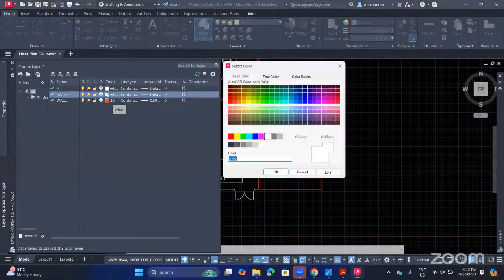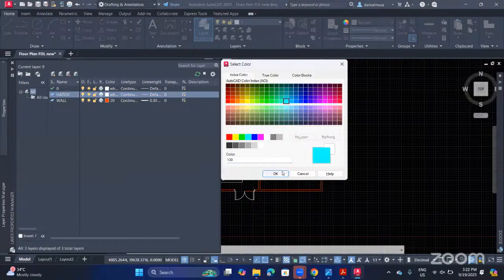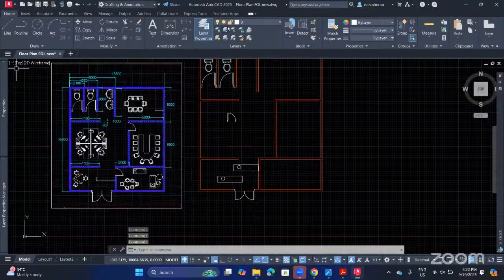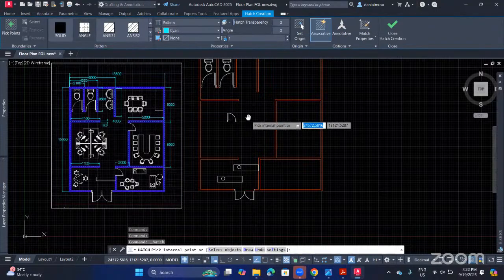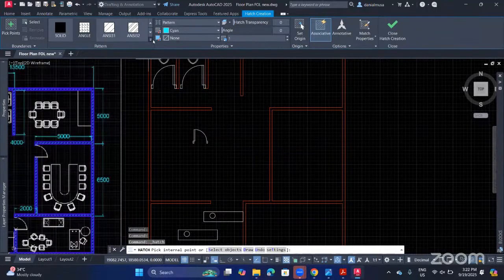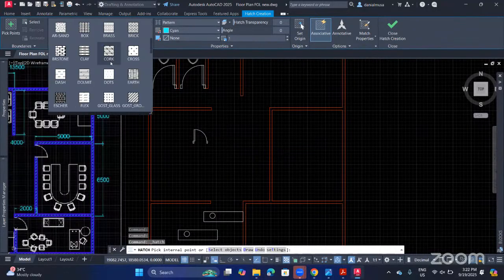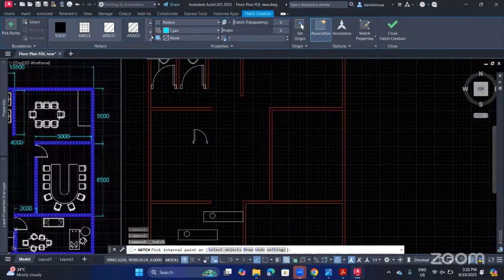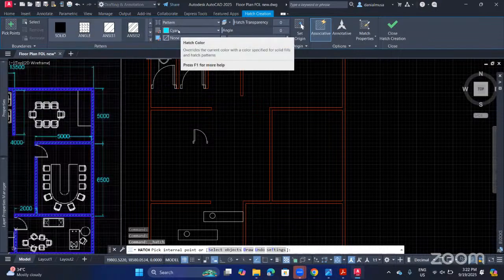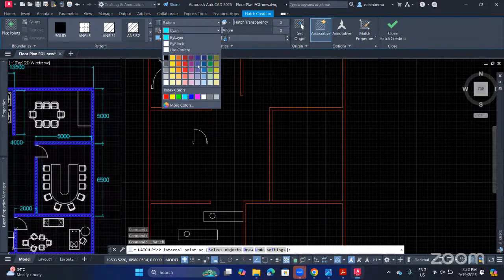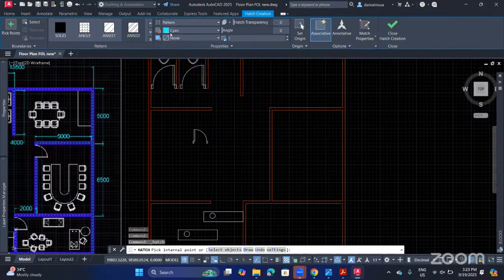Okay. In here, a color you can just simply put. Alright, so you must go to the hatch. Okay, just click it. And here is the style of the hatching, so you can choose many styles you want. But I like this, so I just choose here. And here is the color I choose, but you also can change to another color you want. So okay,